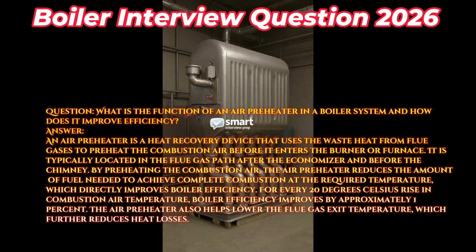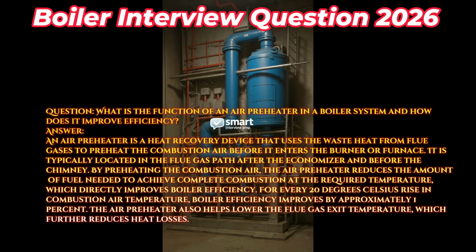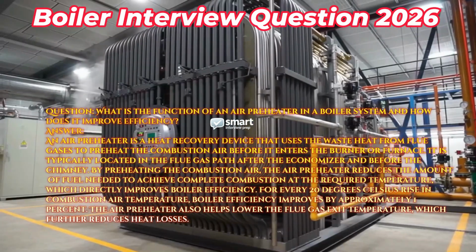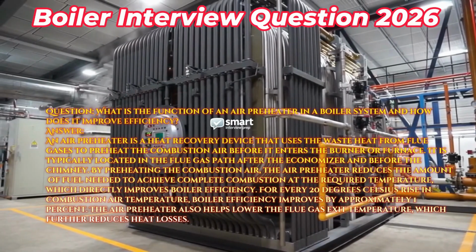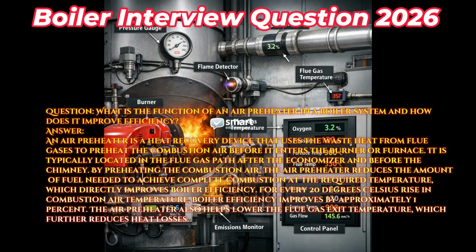Answer. An air preheater is a heat recovery device that uses the waste heat from flue gases to preheat the combustion air before it enters the burner or furnace. It is typically located in the flue gas path after the economizer and before the chimney. By preheating the combustion air, the air preheater reduces the amount of fuel needed to achieve complete combustion at the required temperature, which directly improves boiler efficiency.